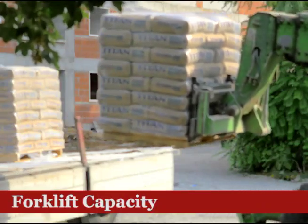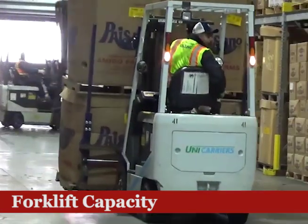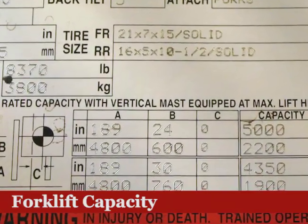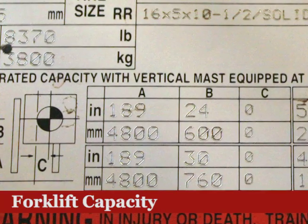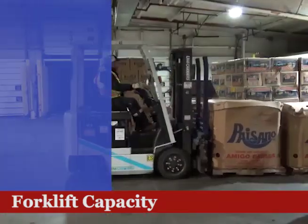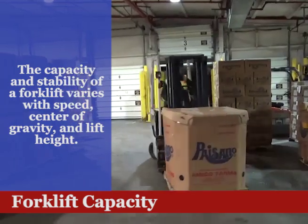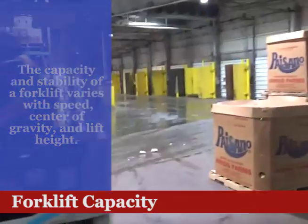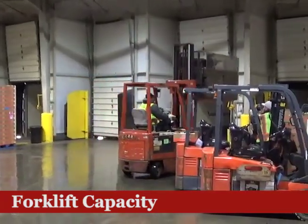One of the most important characteristics of a powered industrial truck is its capacity. That should be pretty easy, right? As long as the weight of the load is less than the rating listed on the capacity plate, we are in business. Unfortunately, it is not that simple. The capacity of a forklift changes constantly, depending on its speed, center of gravity, and lift height. An operator must constantly evaluate these conditions, to ensure that the vehicle is not overloaded.